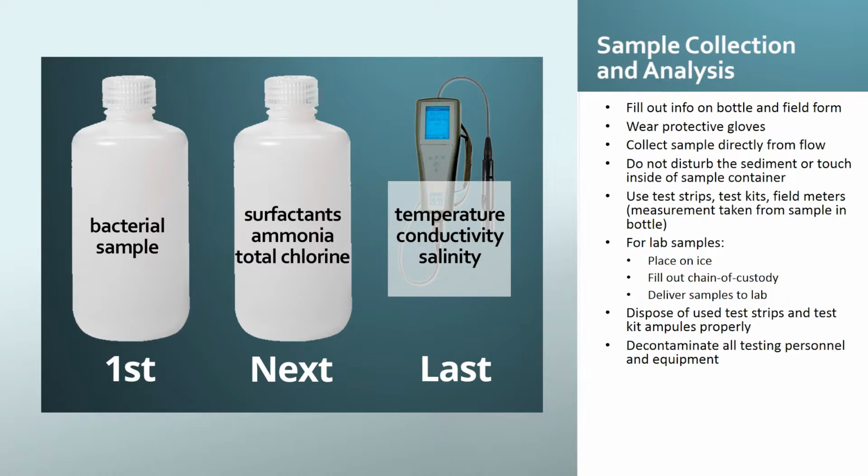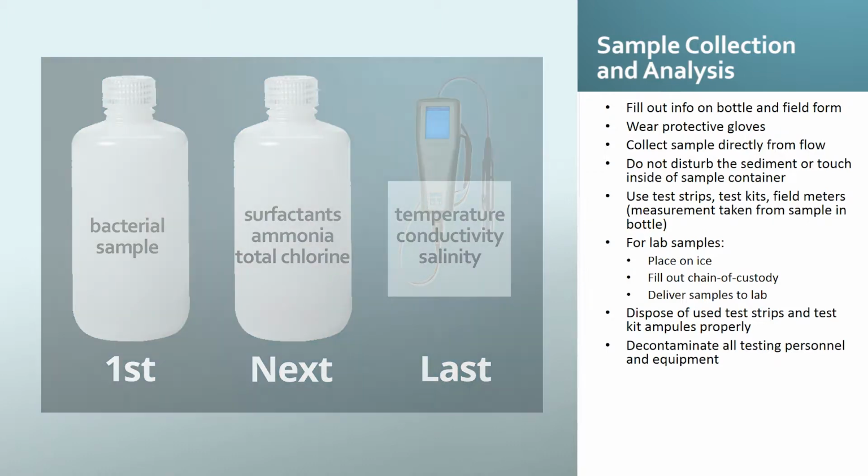Surfactant samples, however, must be collected in opaque 120 ml bottles and kept on ice in the darkness of a cooler until analysis, since some surfactant compounds can degrade under ultraviolet light. Maximum holding time is 48 hours.